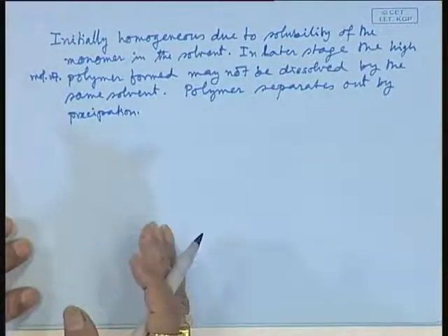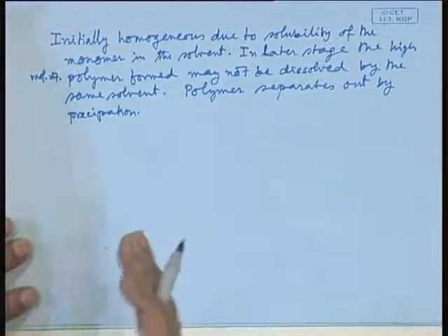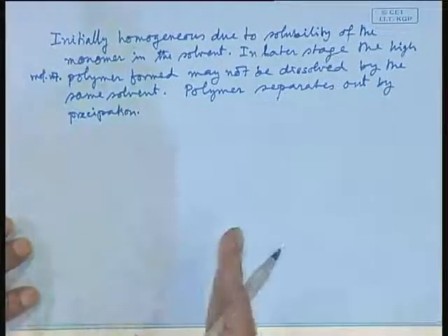After certain growth, when the polymer is of adequate molecular size, it comes out of the soluble phase, polymer precipitates out. So, that is also a solution polymerization, but you are getting polymer isolated. It is an easy, simple technique, and you can avoid the polymer isolation step by solvent evaporation, distillation, stripping, etc. In that case, it is advantageous.